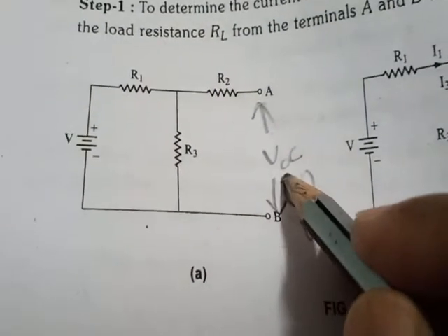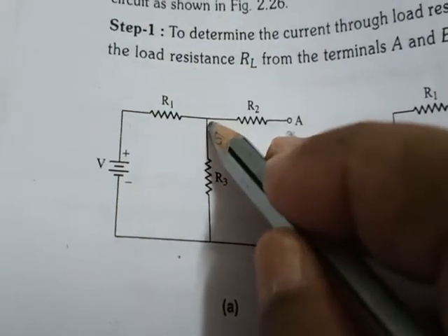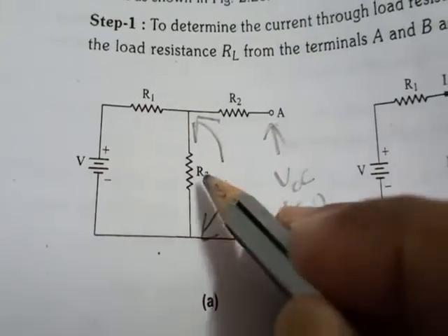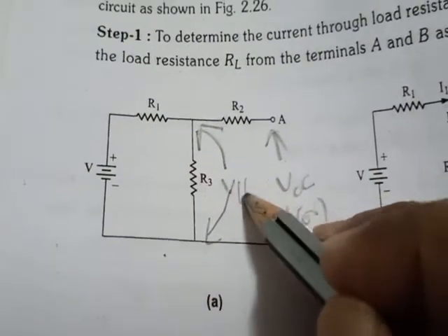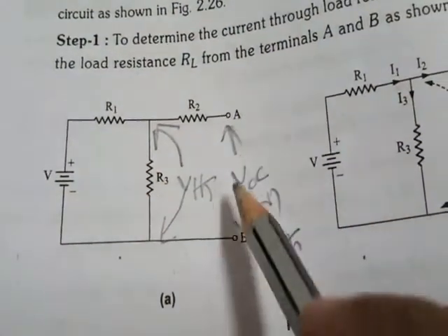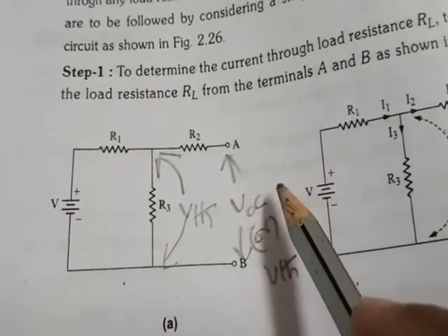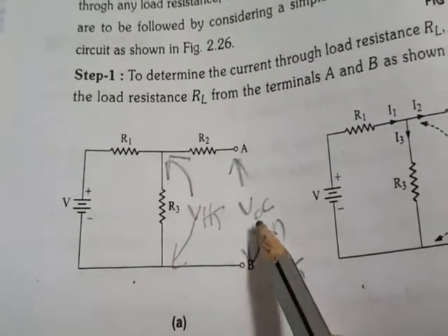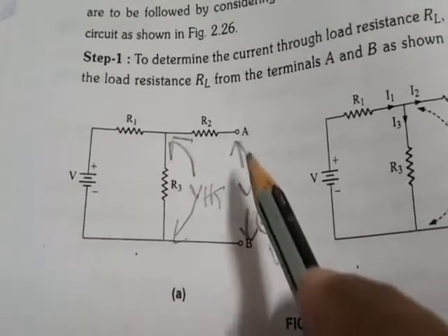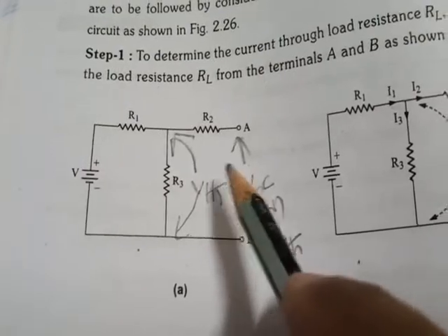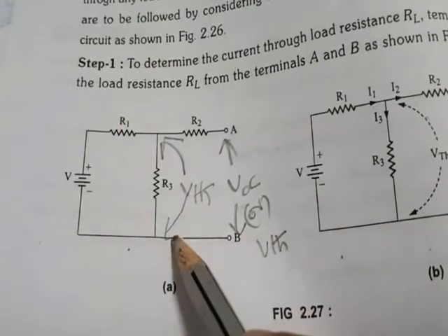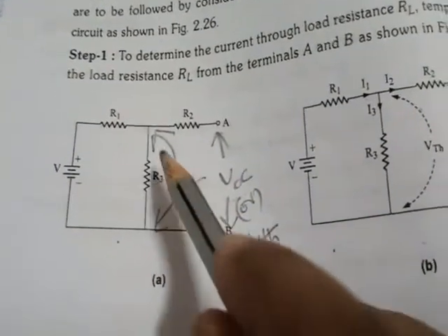How you have to find it: you can find Thevenin's voltage across this resistor, that is, across the open terminals, we have to find the VTH. So this is how you have to find VTH, right? This is a circuit. A and B are the two terminals where the load resistance is temporarily removed, and this behaves as an open circuit. So the voltage across A and B is VOC or VTH. So in this step you need to find Thevenin's voltage. That Thevenin's voltage can be found across this resistor R3. So simply you represent VTH like this with arrows across R3.